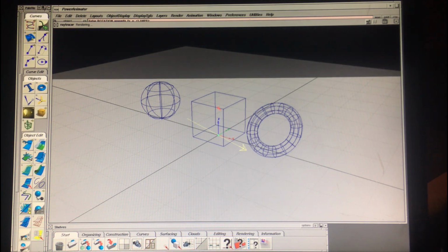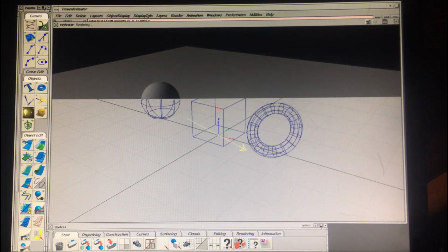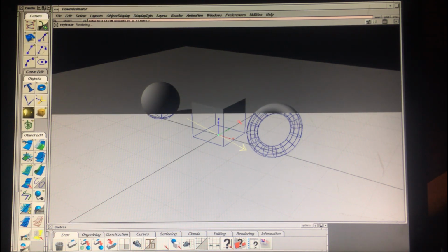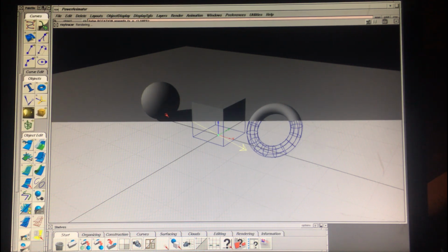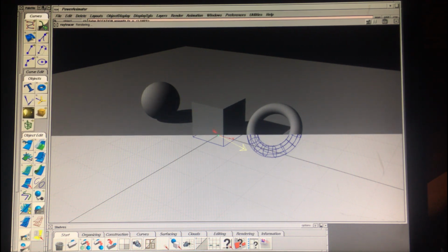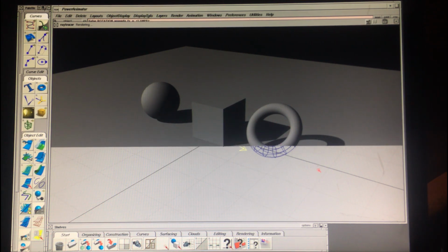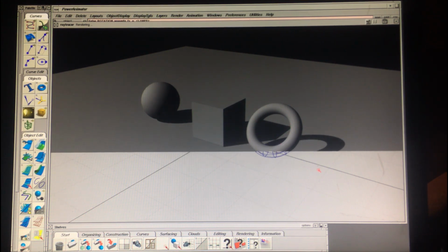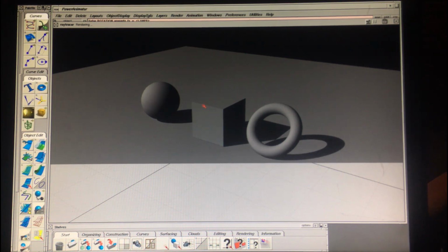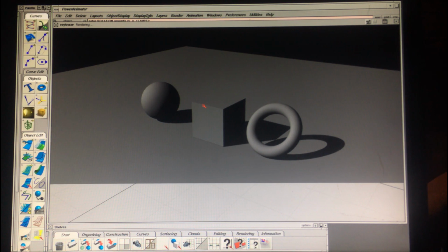Because I turned the anti-aliasing up from 0, it's probably taking a little longer than it should. But there's our gray shaded. Oh, you can't see the top of the box because it has the same gray shade as the floor. But you can see here it's going to put some shadows, and because it's a distant light, they're always going to be sharp. So it's literally like a cucaloris, a cutout shadow. What we'll do is switch this over to a light that gives us a soft shadow.